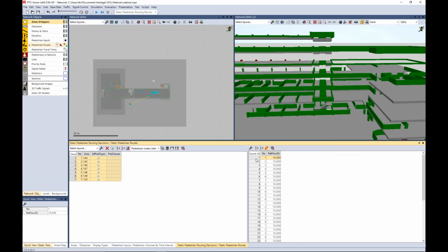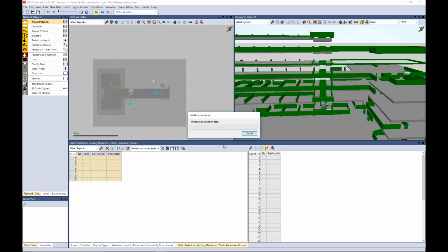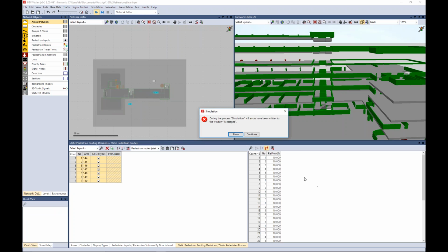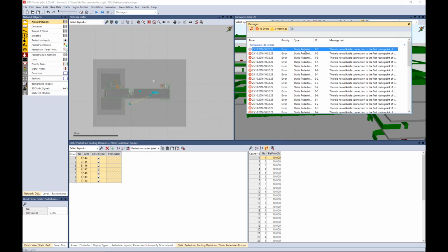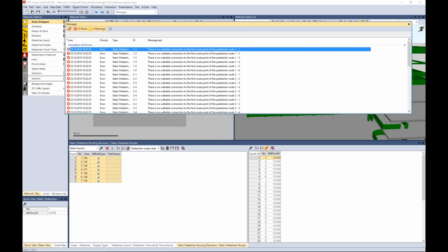So that's the routing system. Good. So maybe now we have a chance. No, we don't have a chance that the simulation runs if I click start. It's just to check if there are some issues. Probably there are. I want them to walk to use the lift. There is no lift, and the staircase which was there in the IFC file also does not exist. So no surprise, it tells us no walkable connection.